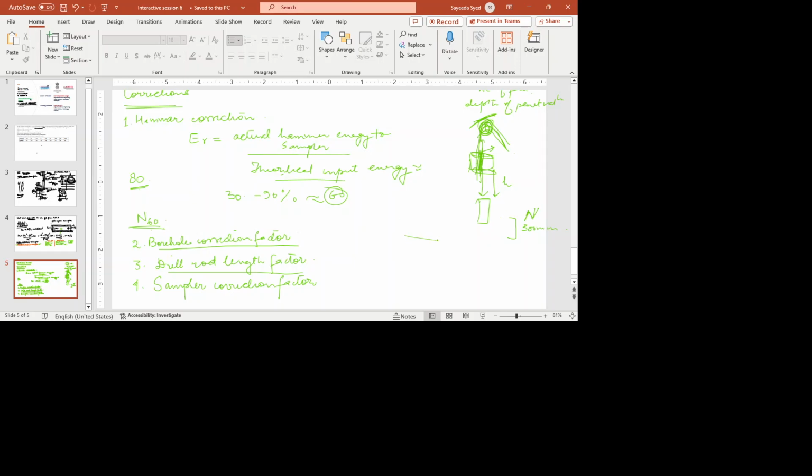So basically what we are doing is, in the strata, we are not inserting the sample by blowing throughout the strata. For example, here we have taken a sample and then we are augering or boring by any other means up to the next desired level for sampling, and then we are again installing the tripod for SPT, and then lowering the sampler, then attaching the hammer.